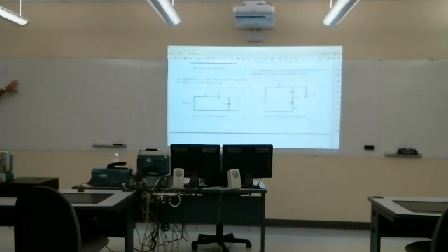So from voltage division, we want the voltage across this device, so it'd be the impedance of this device over the total series impedance. That works in a series circuit. You could alternatively find the total current by dividing VI by the total series impedance, take that current, and multiply it by that impedance to get that voltage.